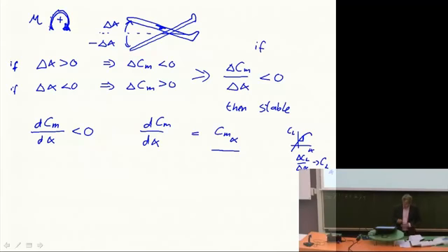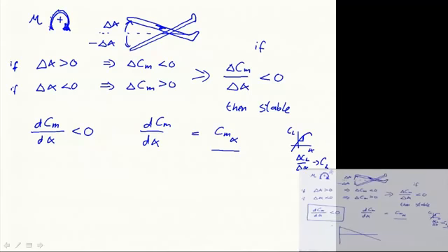So a stable aircraft, we know, has to satisfy this relation. And of course it also has to be trimmed. If you want to see what it means that it's trimmed, basically here we say that it has to go down. The Cm of the aircraft has to go down when alpha increases. This is basically graphically the same thing. If Cm alpha is negative, this means the curve, the line, it's a nearly straight line, has to go down. But also, there has to be a point where it's 0, because that's the equilibrium. In other words, we call this the trim point.